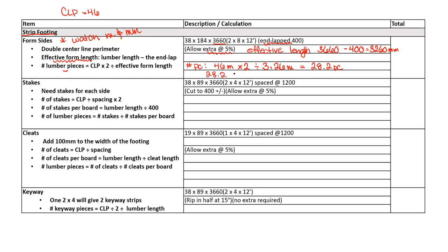5% is 100% of what I need plus 5% more. So it's like multiplying by 105% or 1.05. That goes back to last semester. So multiplying by 1.05. Now this is going to be our final number, so we will round it. We get 29.6, which rounds to 30 pieces. So we need 30 pieces of lumber altogether. So you can see how this just kind of keeps organized for us.